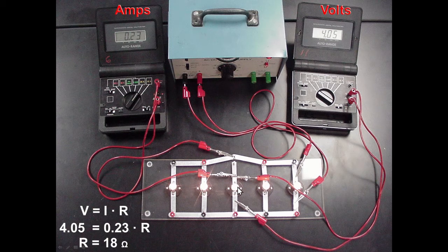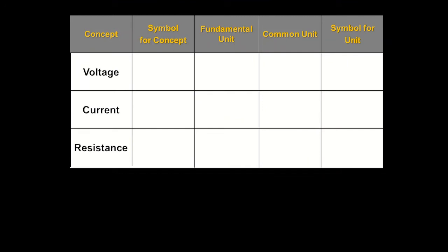Now, if I had unscrewed that light bulb and let it cool down and then set my multimeter to measure its resistance, I would have gotten a resistance a lot less than that. And that's because that extra heat of it glowing red hot there gave it more resistance than if it was cool. A light bulb filament is non-ohmic.